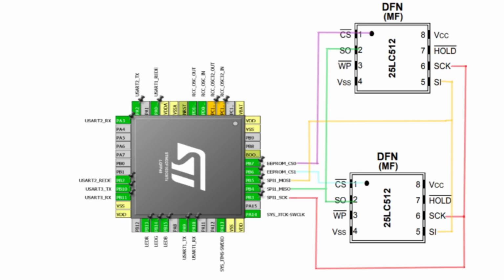Also add a larger bulk capacitor, 1 uF to 10 uF tantalum or ceramic, somewhere nearby on the board's 3.3V rail. This provides clean, stable power during the fast current spikes of SPI communication. Fourth, pull-up and pull-down resistors. As mentioned, a 10K pull-up on each CS line to VCC is good practice to prevent unintended activation. Also, check datasheets for pins like HOLD or WP on flash memory. They usually need pull-ups if unused. Don't leave inputs floating.